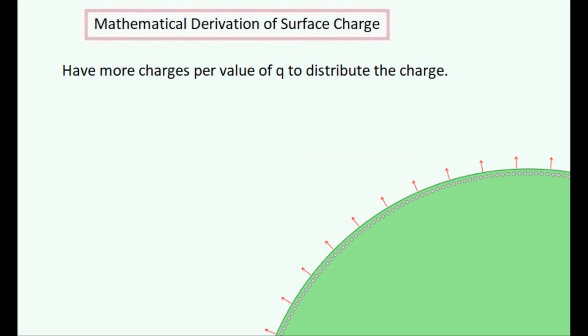Another idea is to have more locations of this charge, so that the charge will be more spread out, but having groups of about 6 or more having the same charge. This will make the charge more finely spread out, without making the matrix grow too large and having problems associated with a large matrix, like for it to take a long time to be solved and being filled with errors.